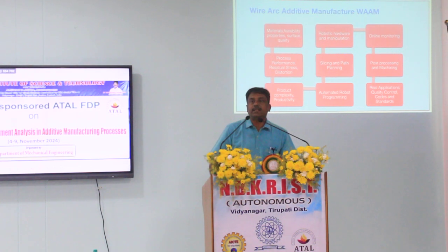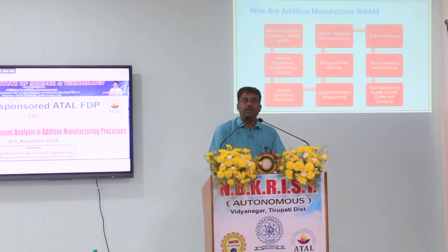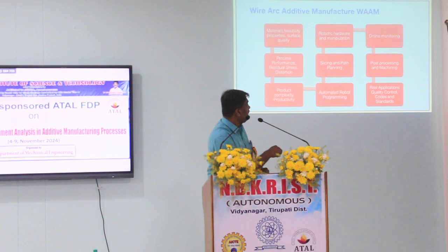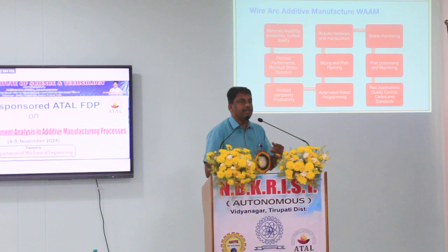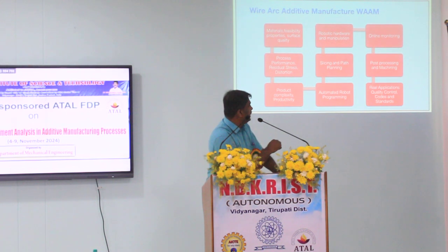We also use extensive online monitoring tools to monitor the defects. Okay, again, I'll come back to that. We also use a lot of AI-based tools for online monitoring. It also gives closed feedback: suppose some defect is forming, you can detect it, completely remake the layer and then start printing again. Okay, good. Once it is done, post-processing machining is important. We machine the surfaces, then get the components ready for end-use applications. Okay, good. So this is the generic process chain.